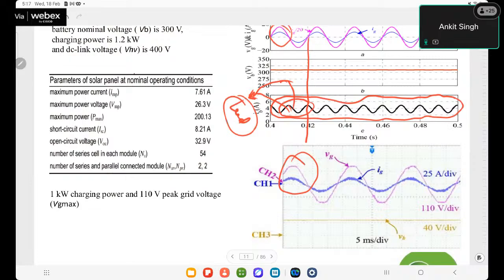I have shown here through the simulations, and I have not added much filter requirement. If you increase the filter, this ripple will definitely reduce in a single phase system also. But as I told earlier, the charger weight and overall cost will then increase.